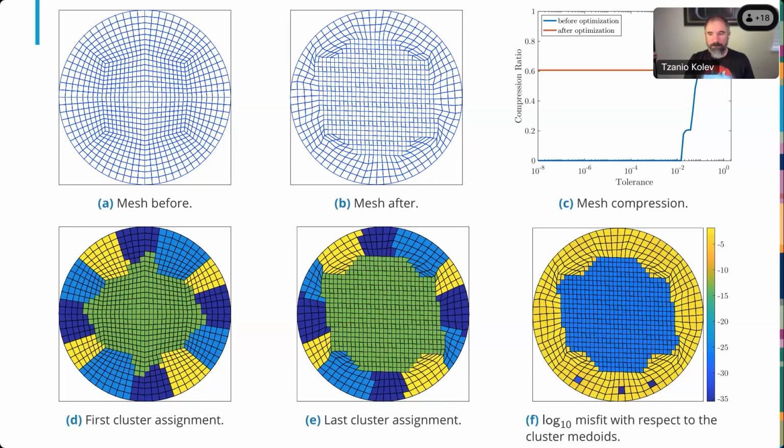Can I ask one more question, Denis? What about polygonal mesh in 2D? Clearly, you will need some convexity, because there are many more degrees of freedom, and your optimization can lead to inverted elements or whatever. Polygonal elements don't have a reference element with a well-defined Jacobian unless you subdivide. Okay, what about triangular meshes? Oh, the triangular meshes are fine.